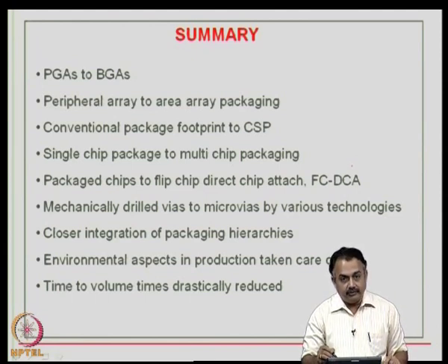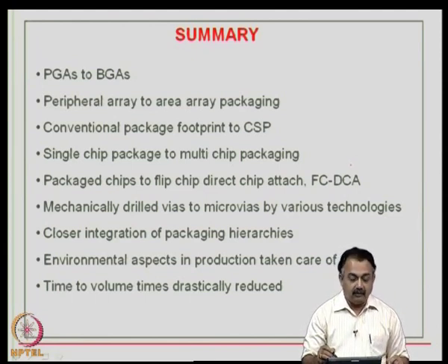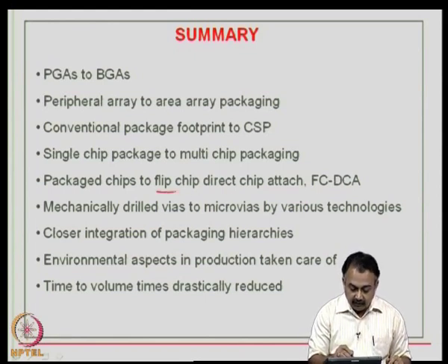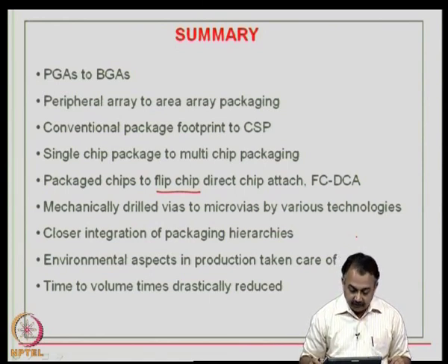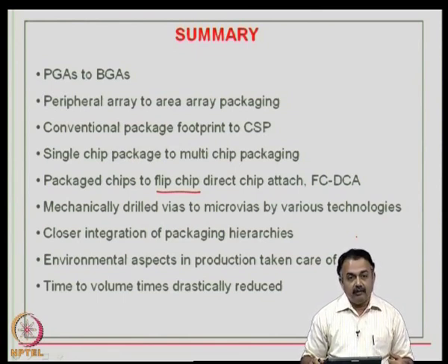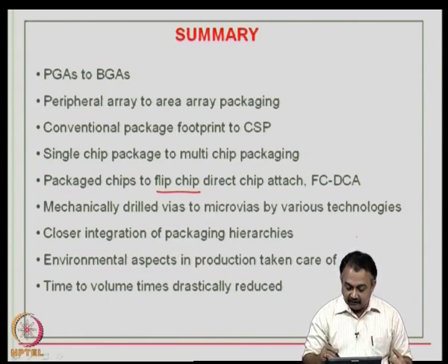Packaged chips to bare die, that is flip chip, C4 interconnect or direct chip attach on board technology is available. So, more designs will come with flip chip, direct chip attach. We are moving away from mechanically drilled vias to micro vias by various technologies like laser and so on.